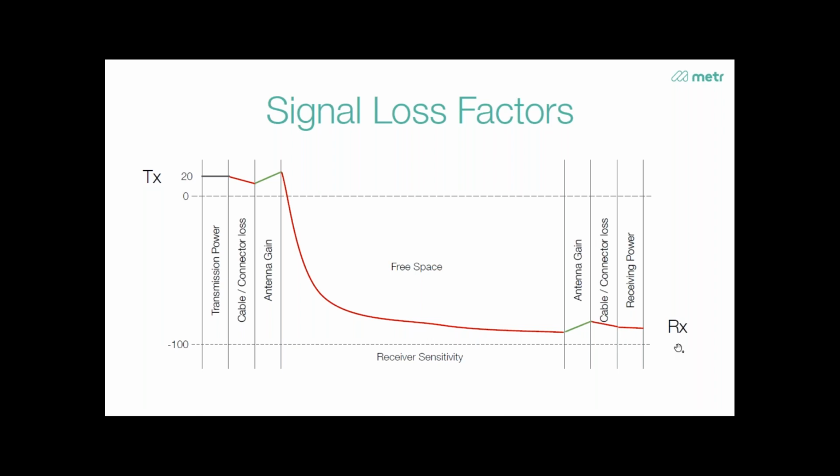But what you usually experience is this is where the numbers are coming from. If you're not familiar with it, if you see a reception or RSSI quality of -80 or -70 or something, that's because from 20, we go through 0 and then go below 0 and end up at -70 or something that the receiver can still recognize and work with.